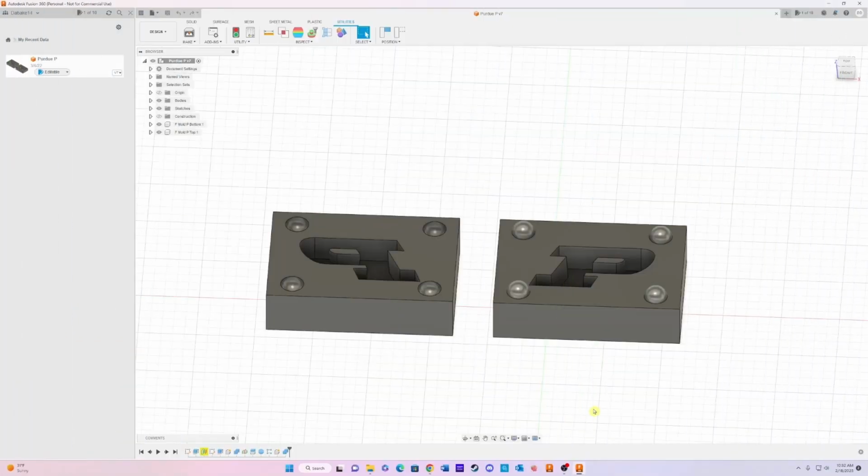Alright, moving on, our next step is going to be in Fusion 360, our CAD software. As you can see, I already have a model created, and if you don't already have one, this is where you'll make one. Our first step in here to get our first file type is we're going to go up here and select Utilities on our toolbar on the far right. Under Utilities, we're going to select Make, 3D Print, and the first thing it's going to ask us to do is select. So I'm going to go ahead and select my entire model.